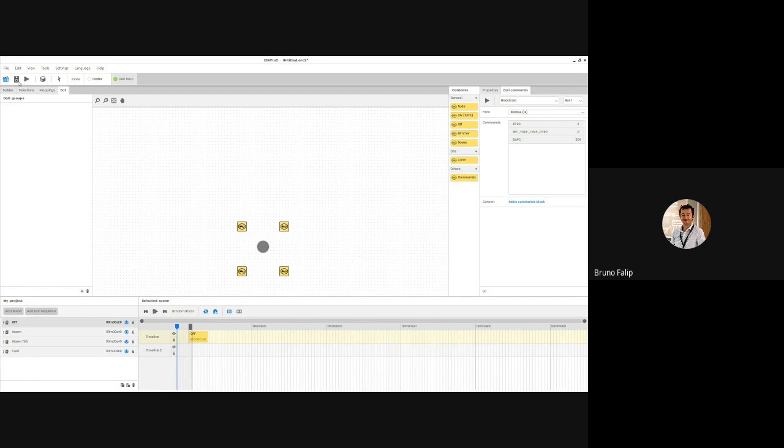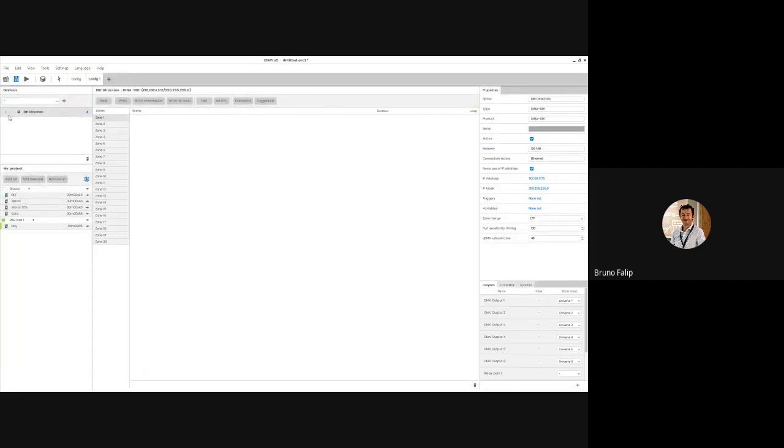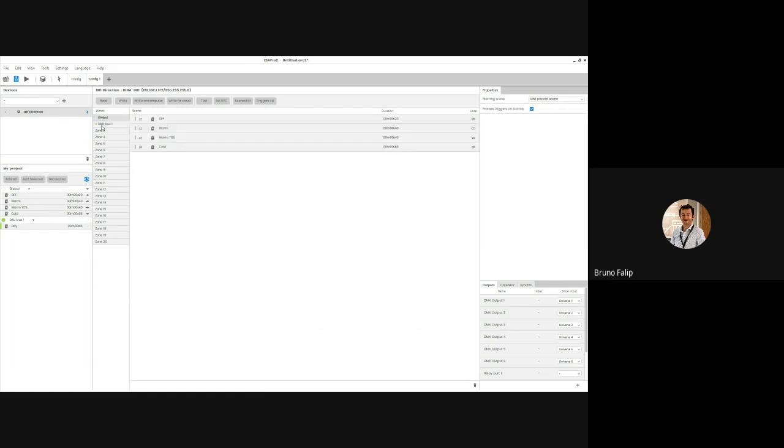So when you move to the standalone tab, where you're going to be able to write the memory, you can see the DINA 1 here. Available scenes are here: global zone, DALI bus 1. If you press add all, you can retrieve your two zones. Remember, there are up to 20 zones on the DINA 1, so you are able to control 20 different physical zones at the same time. So you can, for example, play 20 different scenes on different devices, of course.